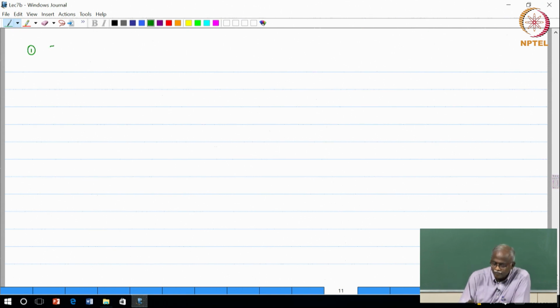So, expansion, sampling rate expansion. I want to ask two questions. First is an observation. Expansion basically inserted zeros, right? So, there is no loss of information. You agree? I cannot lose information in the expansion process.